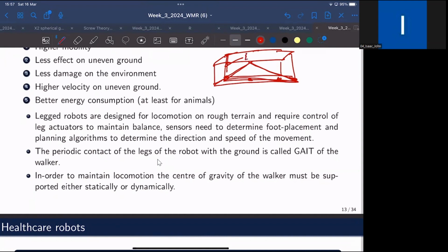But due to some external payload, or if you are putting some sort of weight, and you are shifting this projected center of gravity outside the polygon supported by all the 4 contact points, then it's not stable, and the structure or the table would definitely fall over. So that is static stability, and dynamic stability is about keeping the robot from falling as the robot is moving from one position to another.